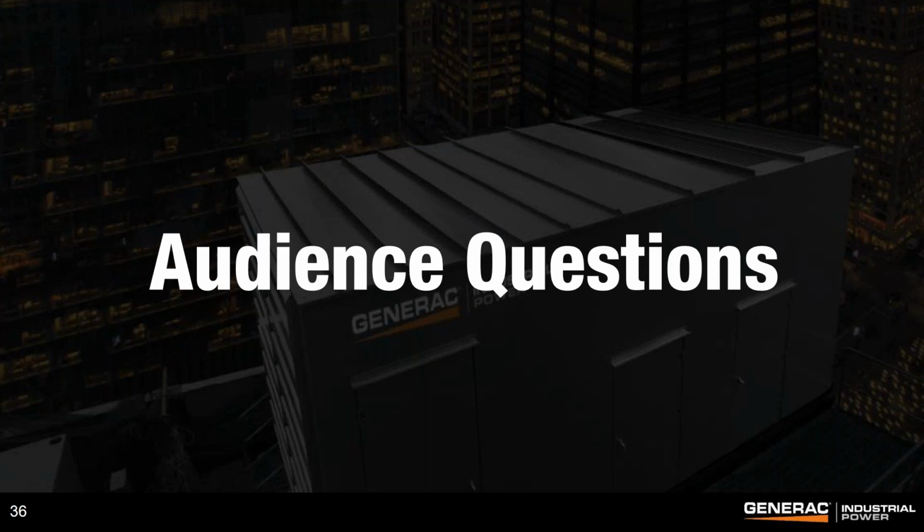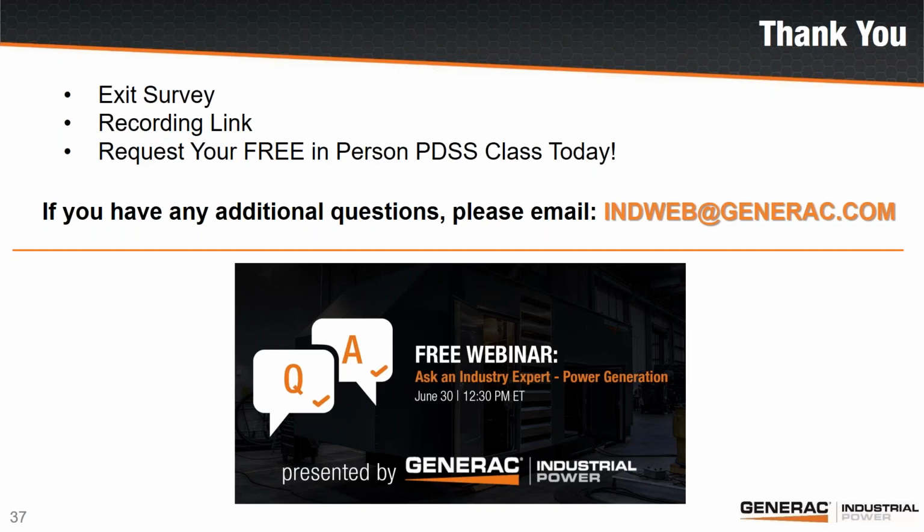And we don't actually see the effect that's trying to be solved on 4-pole switches. We don't get nuisance tripping on 4-pole switches in 3-phase systems. So given the huge population of 4-pole switches and no proven cases of issues there, I would say stay with the standard proven 4-pole technology and don't add the complexity, because it doesn't seem to be warranted in the field.